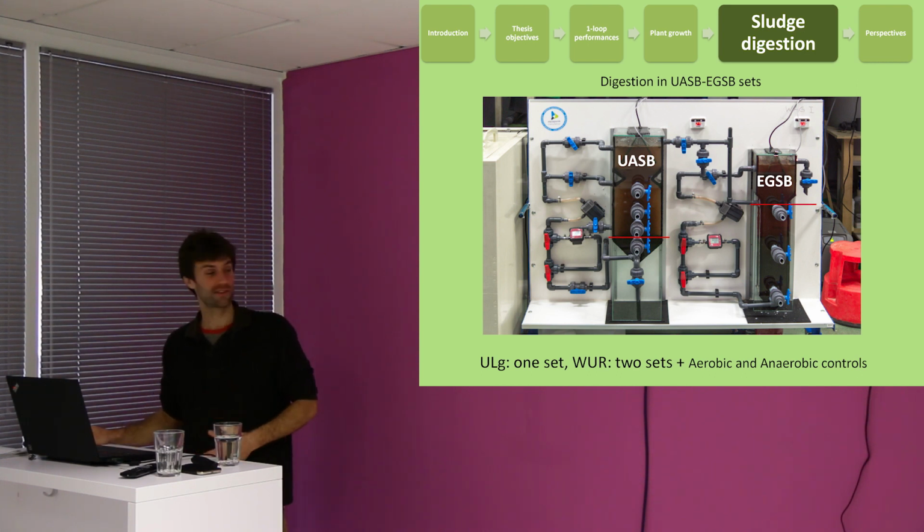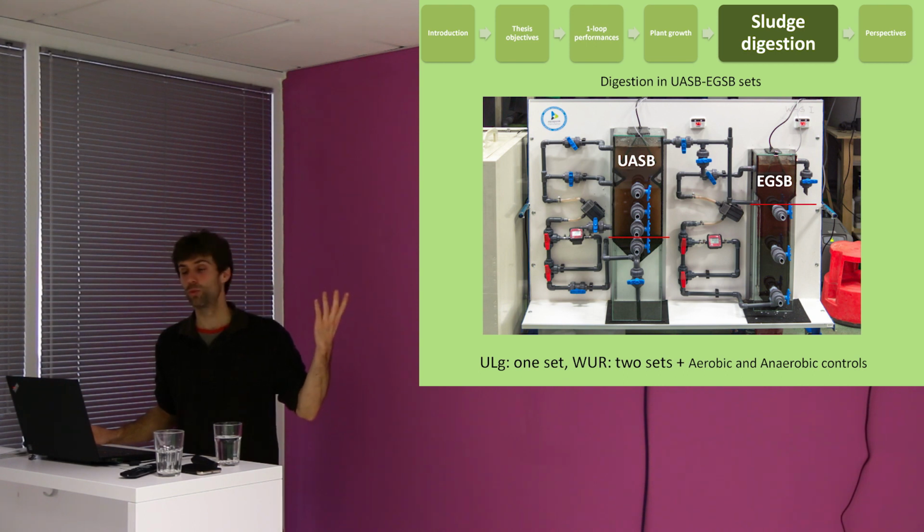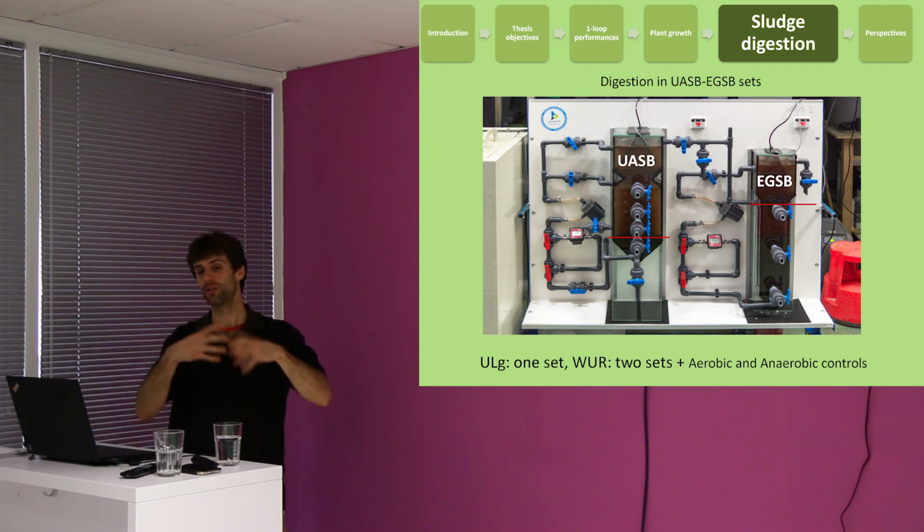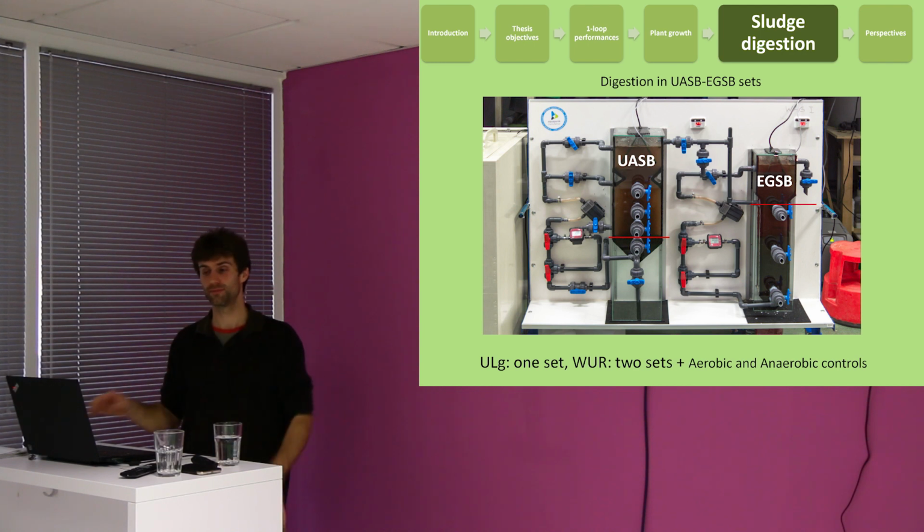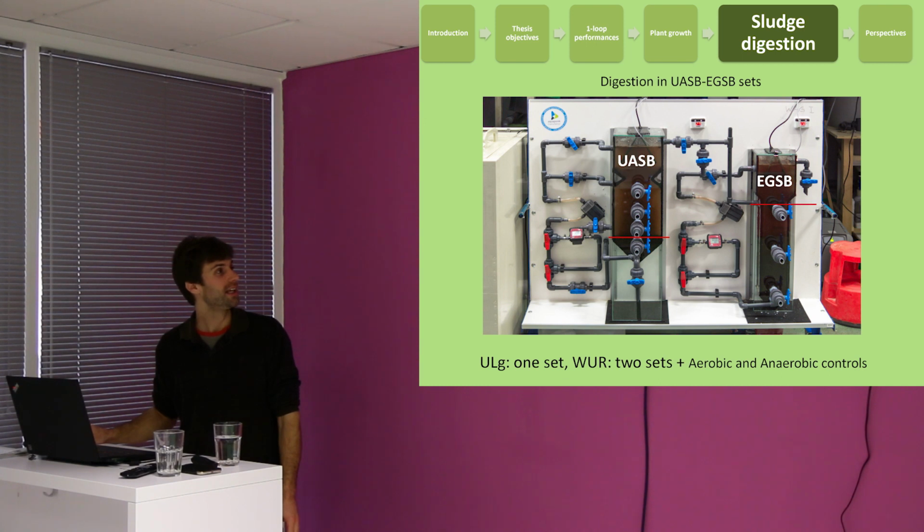It's an anaerobic reactor, and how it works is you have a recirculating flow into it. So the pipes, you have the pump here, so you have a constant upflow. The pump pushes the water here, and you have what we call a sludge blanket. The sludge is at the bottom and it's slowly mixing, and then it goes up there and comes back again. This kind of bioreactor also produces biogas, so you could recover methane to produce energy. This is an EGSB.